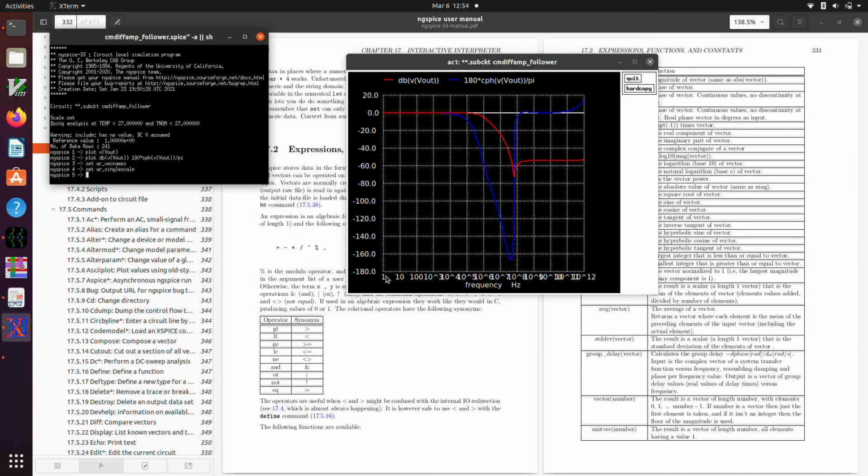Scale is what Ngspice calls this x-axis label representing the thing that is swept. So if we only want that column appearing once instead of once per vector we write out, we want to set this variable single scale, which, if we don't specify a value here, these variables are assumed to be Boolean variables, and setting it basically makes it true.